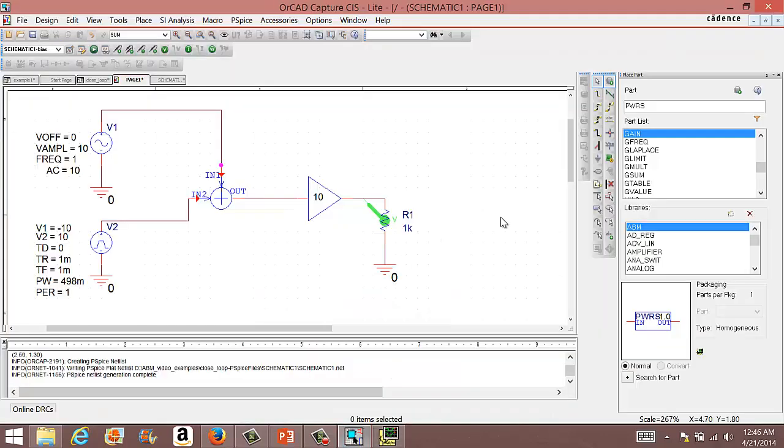Again, the ABM library has unlimited ways you can define a system. You have if statements, you can model it adding, subtracting, multiplying different signals. You can also make independent sources, but there are so many different ones, it has a lot of capabilities. So you should explore those and model your system depending on what your input and output is.